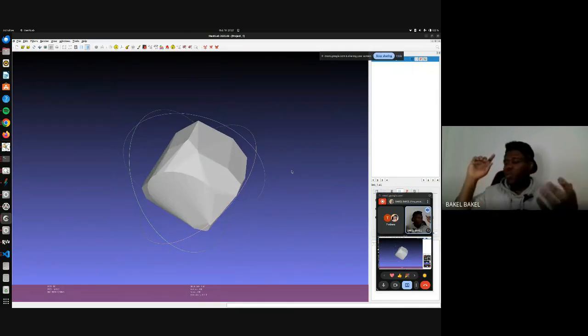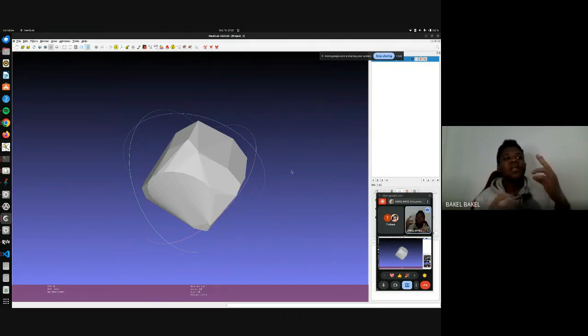We don't need the circuitry, we don't need the wirings, because all we need is something to tell us visually that this is a motor. Any motor characteristics, like speed or RPM, we can always specify and run in Gazebo. We can tell Gazebo, you see this motor, the maximum RPM is going to be 3,000, or the minimum is going to be this, the input is going to be this. Gazebo will simulate it without having to know the internals of the motor.